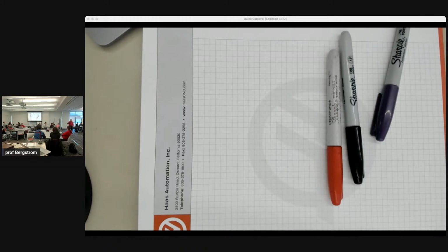And you have to do this step after doing the set the tool and the work offsets. You're the star of the show today. Simulate on the controller. That's what I was thinking of. So simulate on the controller, and we talked about that. It can tell you, did I put the part too far over? Did I load the wrong program? Is it the right program? And then, are the feeds and speeds within the capability of the machine? Because it'll alarm out at that moment.